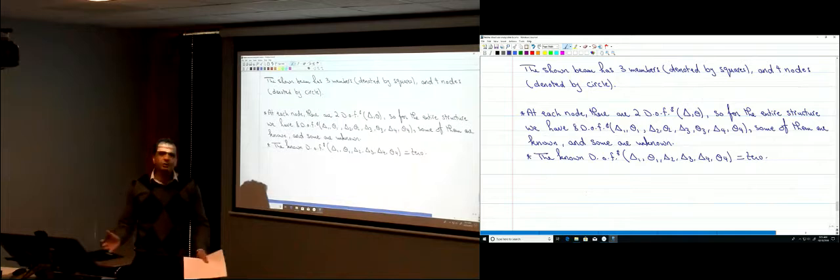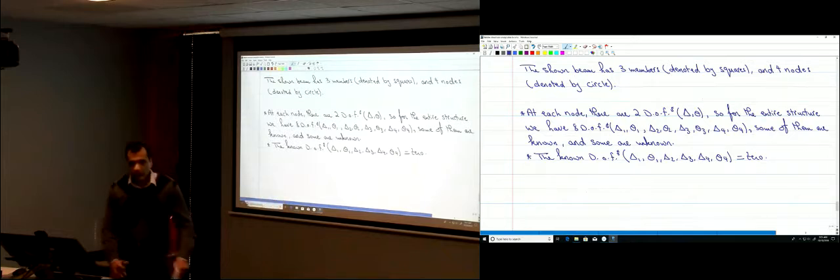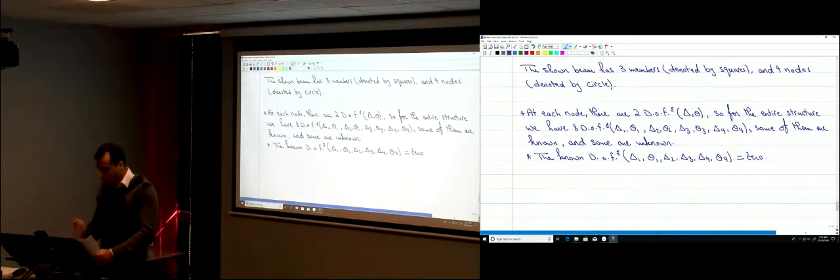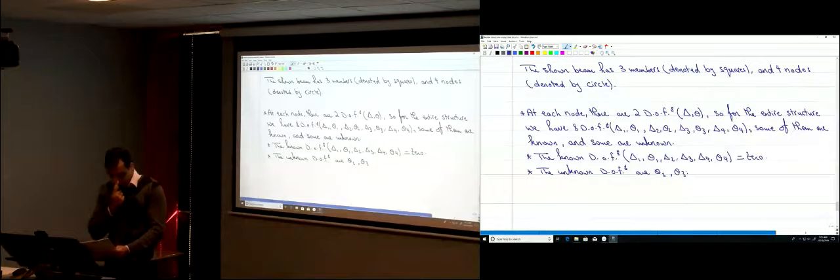Exactly as we did in the slope deflection method, we had those kinematic degrees of freedom. We were just counting the unknowns. But here, I have 6 that are known. They are zeros, okay? And now the unknown ones. What are the unknown degrees of freedom? They are theta 2 and theta 3.